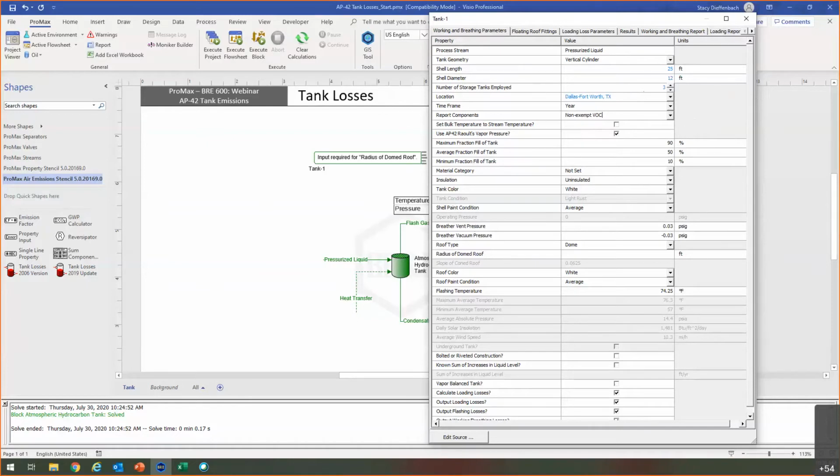What is the basis for ProMax climatological data? Good question. So we have compiled the new AP-42 table of all of those places. We've also grabbed information from the original AP-42, the 2006 version, and the TANKS 4.09D, since they had additional meteorological data that wasn't in the 2006 version of AP-42. So we've taken all of that meteorological data and put it into ProMax. We've grabbed it all from the EPA or from the documentation given for those, so we haven't pulled any random ones ourselves.